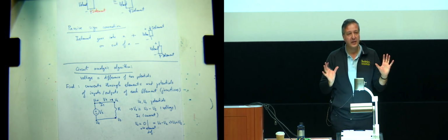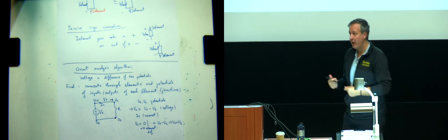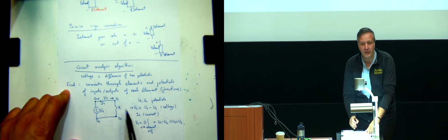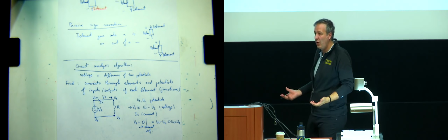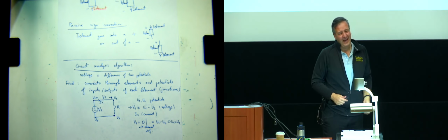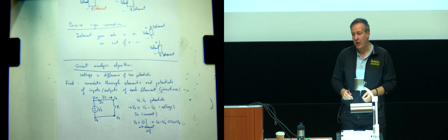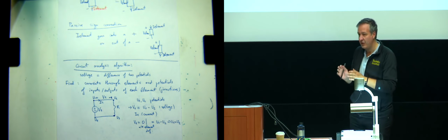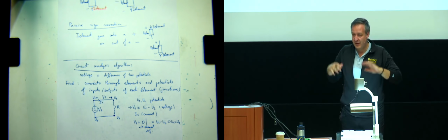Okay. Now, this is actually pretty interesting. It means if my quest is to solve for potentials in the circuit, right, that was the algorithm, then if I have a wire in the circuit, it's really extra work for nothing to solve for the potentials at its two ends, because I always know they're the same, just from the definitions of things, nothing to do with the circuit. So if that's really true, and I'm really lazy, I don't want to explode my space of the circuit solve by treating wires as separate elements, right? Wires are just solved by definitions, nothing to do with the circuit.